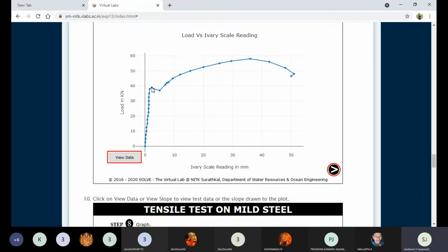Once yield occurs in a ductile material, it does not mean the material will completely break. It still has the capability to deform, which means it can withstand the applied load. Brittle materials will not withstand, but ductile materials do. Even when we reach the yield, they can resist the applied load, and that we call plastic deformation. Even after the yield, they are still withstanding.